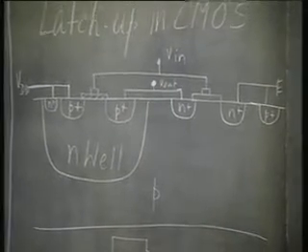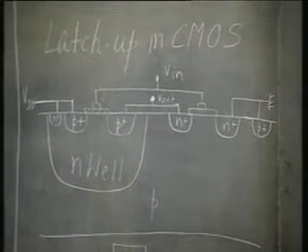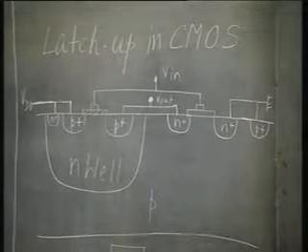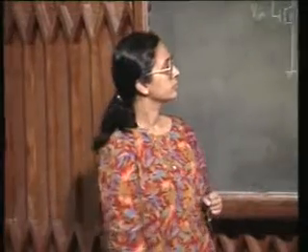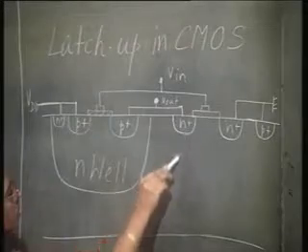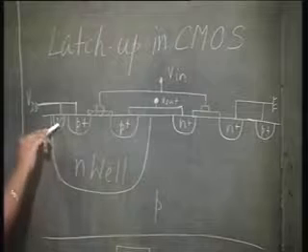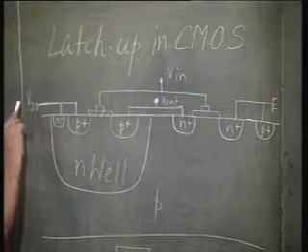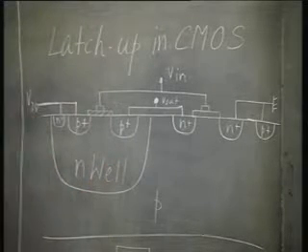That means, if I look at this NPN transistor, the emitter starts to inject electrons in the NPN transistor, right. Where will these electrons go? They will flow to the collector. Agreed? So, it is going out here through the NPN and then it is getting collected here. This is positive, plus VDD, electrons are getting collected and going out through this.